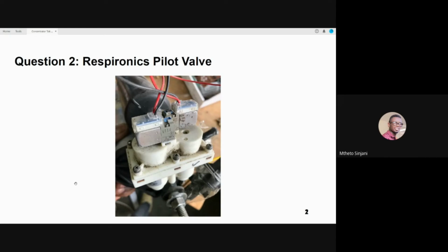Secondly, if air is passing through one sieve bed freely and it sounds blocked when it's passing on the other sieve bed, it's possible that one of the valves is faulty, or one of the beds is blocking the air. So if you have lumps inside the sieve bed, it might be blocking the air. Else, if the compressor is blocked, either way, this might indicate that the sieve beds are not in a good condition, and you might need to refill with new zeolite. So remember that if the pressure in the sieve bed does not reach what the valves need to switch, then the valve will not switch.